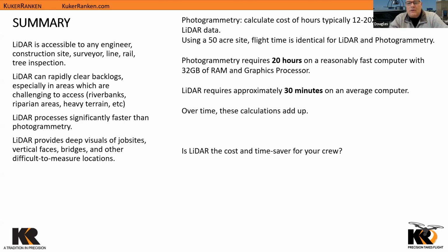On the other hand, LiDAR can cover that very same area and process and spit out data in about 30 minutes on that same computer. So again, that computer horsepower time saves you a tremendous amount of money on the back end or back in the office. Your field time is going to be somewhat similar. Remember, with photogrammetry, we have to have very tight overlap. When we're dealing with LiDAR, we don't need tight overlap. So we can save some time on the flight, but the processing time is where all the difference can happen.